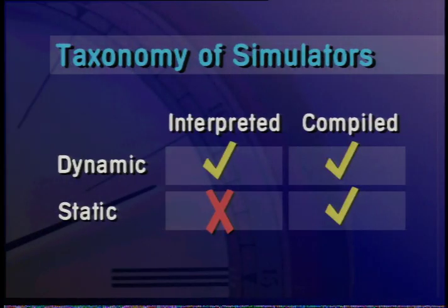In the case of static simulators, there are really no examples of interpreted simulators. They are all compiled. In fact, this class of simulators has often been called levelized compiled code simulators, causing some confusion with dynamic compiled simulators. Dynamic simulators are a much larger class and the more standard type of simulator. This is due to the semantics of the HDLs, which can represent more real circuits. The semantics of all the popular HDLs require dynamic scheduling.